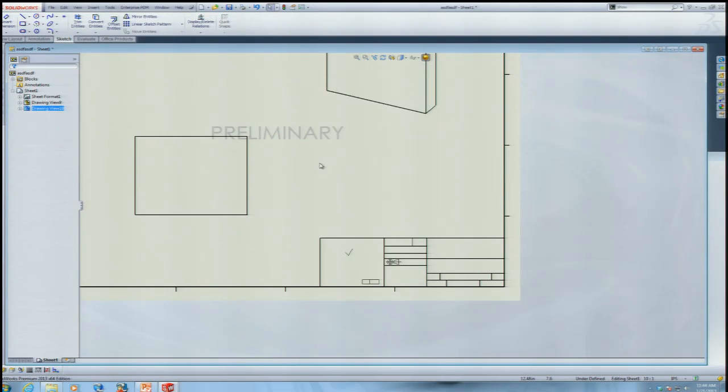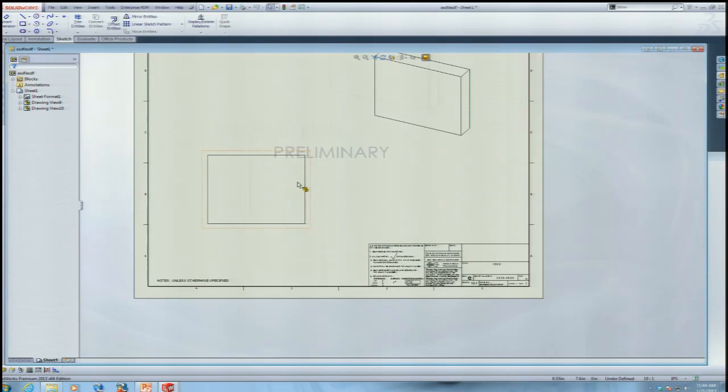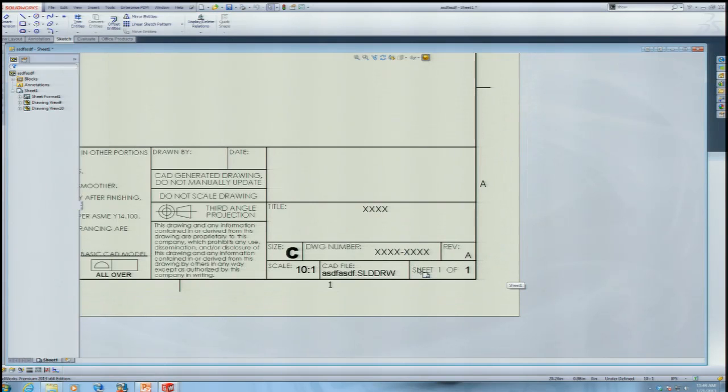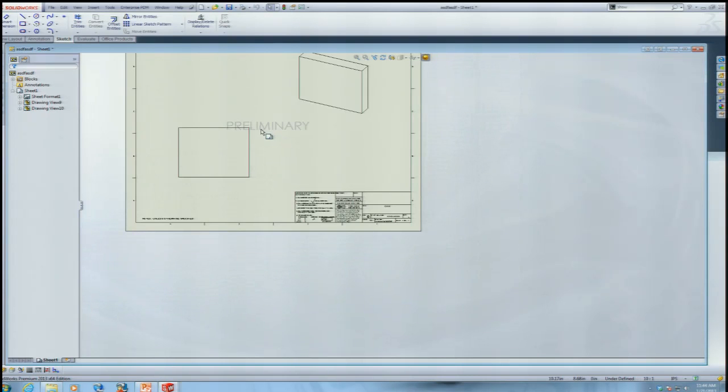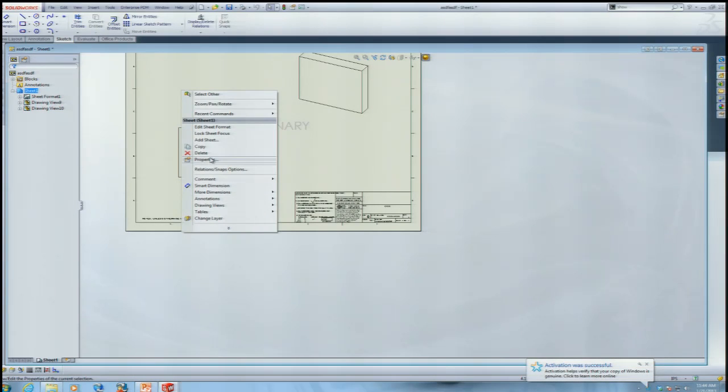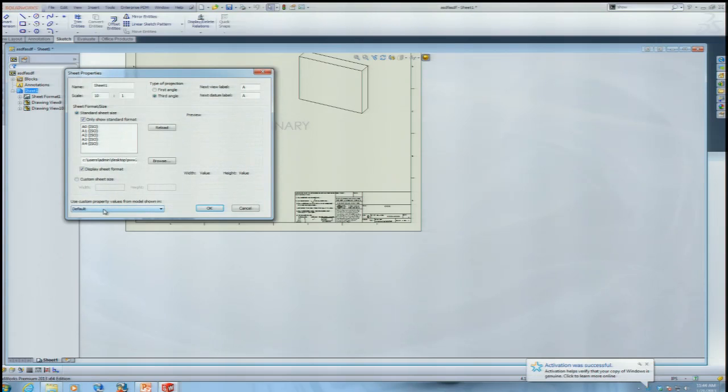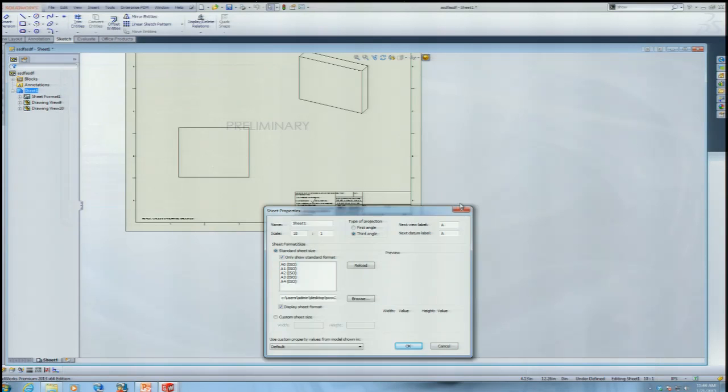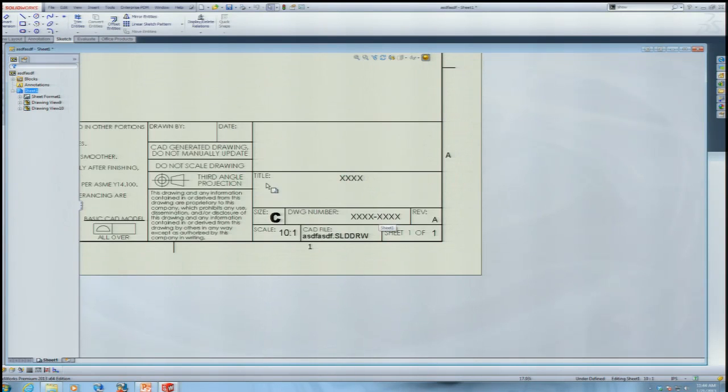And if I were to drop in a file, a drawing view, notice it automatically starts populating right here. And I didn't even have a predefined view in that case. So it's smart enough to know that even if you don't have predefined views, it's going to take the view with this name, the first view of the file. In fact, I think it probably would be default. Yeah, default. So if you choose default and you drop a file into your drawing, it will automatically pick the first drawing view and pull the property values from your title block into that property view.